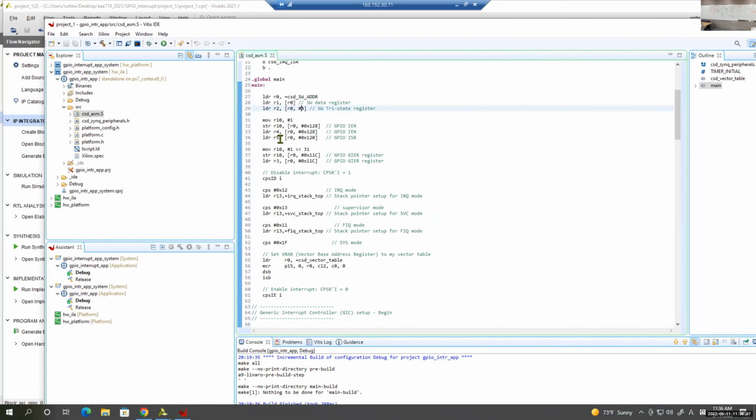And the thing is, here, the same register setting. We are using interrupt ID number 61, and you need to find out which register you have to program to set the priority for ID number 61. Okay? And the target also, in this case, the target is important because it is a shared interrupt. So I have to specify that the interrupt should be sent to only execution CPU0.